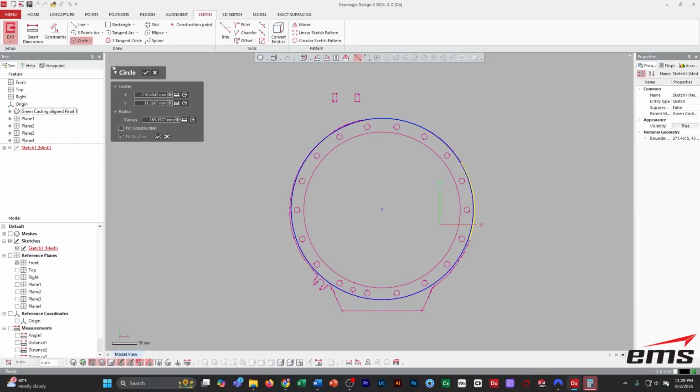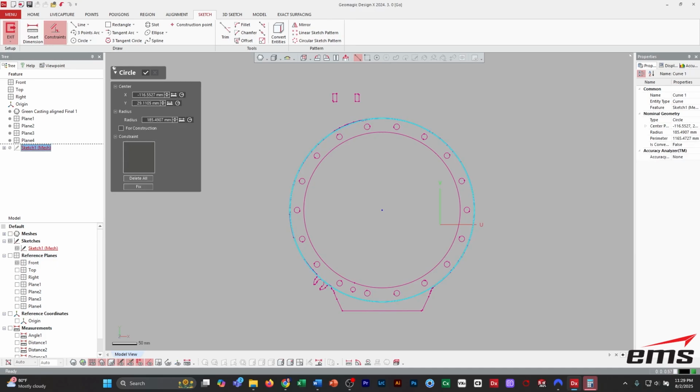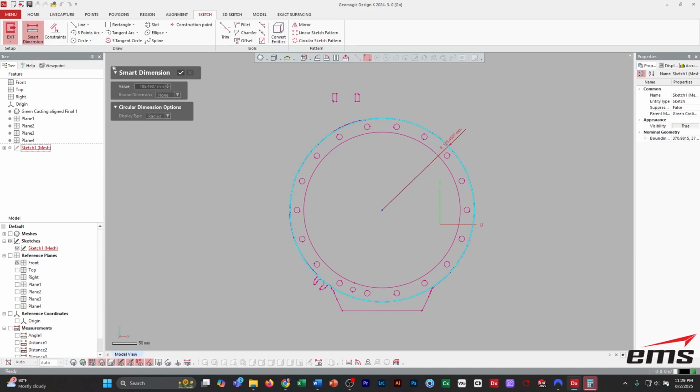So what I can do, it's kind of broken up because it's probably not a very smooth circle, but I can sample some of the segments and it'll keep adjusting this circle because now what we have in blue is a perfect circle fit all the way around there. Now, once we have a piece of geometry, we can add a constraint to it. And in this case, oops, not a constraint, sorry. We already know it's a circle. A dimension, and throw a radius on there. And I'm going to hit OK.